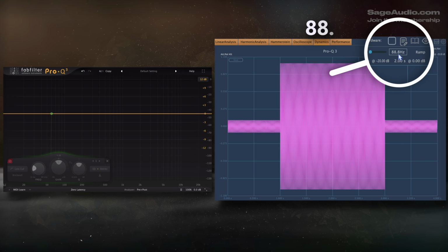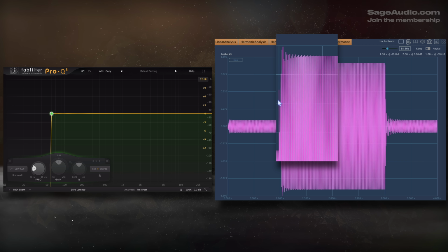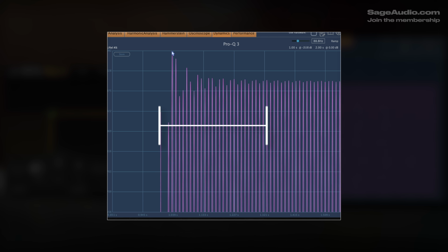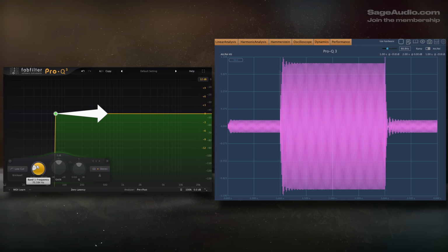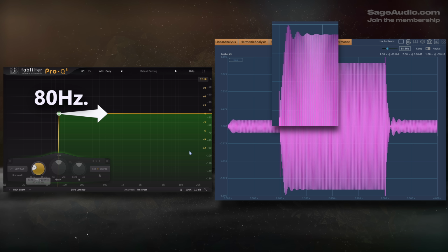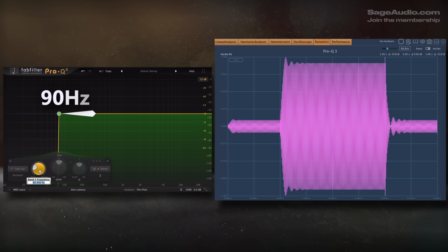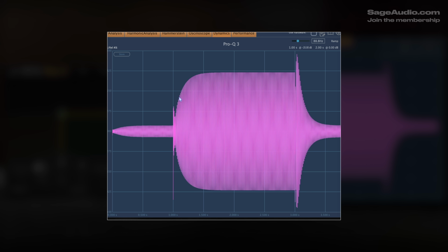But as I've come to expect, this issue is even more prevalent in low frequencies. If I alter the sine wave to 88 Hz, then with the cutoff set around 60 Hz, we'll observe alterations to the amplitude just like before. However, instead of taking 20 milliseconds to return to the accurate amplitude, it takes close to half a second. And watch what happens as the cutoff approaches the sine wave's frequency. Again, with the cutoff at 80 Hz, we'd expect to see no alteration to the dynamics of a higher frequency. But the changes are significant and they only get weirder. With the cutoff at 90 Hz, notice this gradual amplification from the quiet section of the sine wave to the loud. Additionally, notice this massive amplitude change when transitioning from the loud section to the quiet.